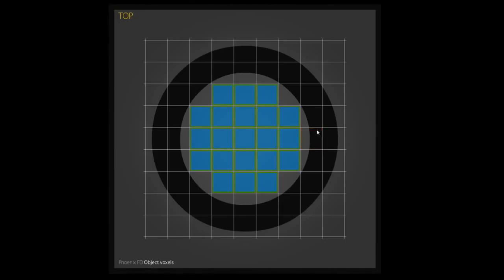And if you take a look at that voxel again, this time you can see that no matter that it's intersecting, we have this voxel filled with liquid. And that's exactly what the inscribed mode does. So it considers the intersecting voxels as non-solid, and it will fill them with liquid.